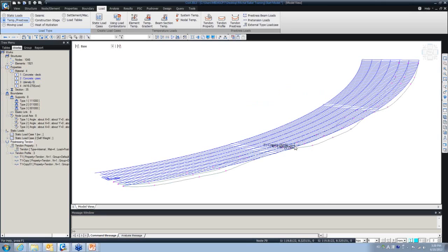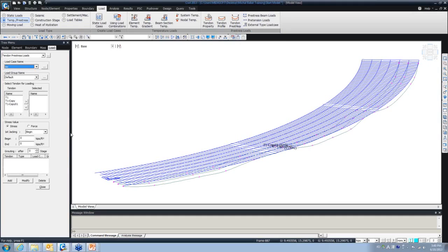I just want to show you what's going on there, and keep moving on, and then show you the other options. Later on, when you want to apply the pre-stressing tendons, you can go with the tendon pre-stress and select, for example, all three of them, and add them to the right box, which is the selected box. And for the post-tensioning, you have options. Post-tension is from one end, from the beginning, from the end, or from both ends. Definitely, when you are post-tensioning from both sides, technically you're going to have less friction loss because of the shape of the tendon profiles.